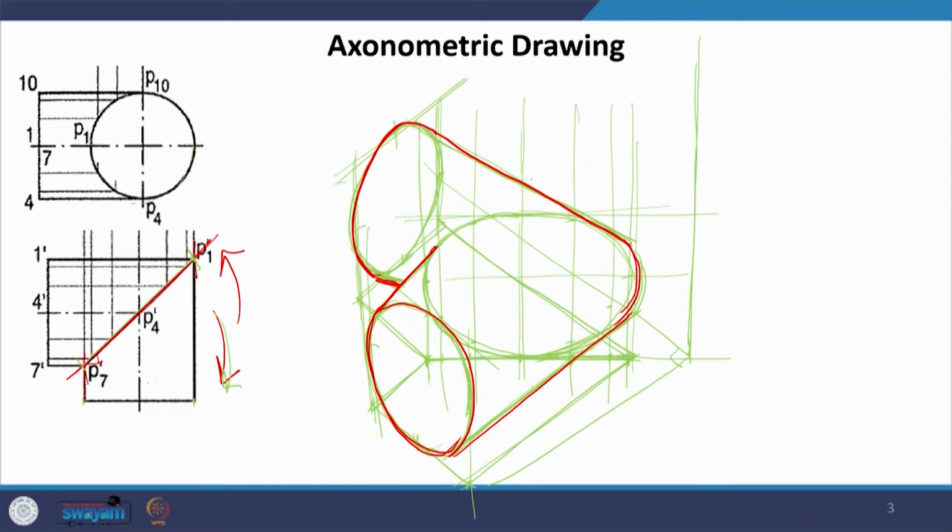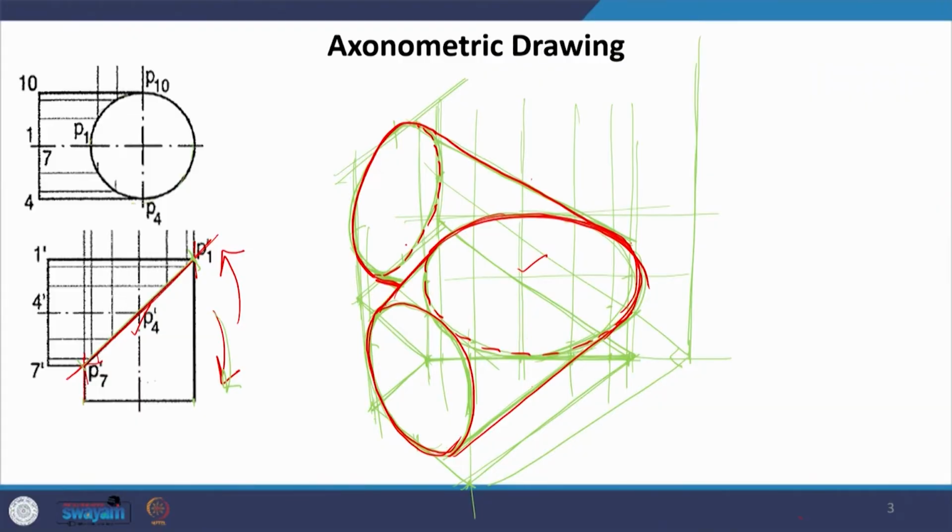And here at this level, we will be actually seeing this curve coming. That is how you will be seeing this combination of two cylinders which are welded, joined at this level, and this is the dotted, the hidden line which is going to go behind. Now, if you can see very clearly, this ellipse is actually the true shape of this intersection, where these two solids are coming and intersecting each other. So, this ellipse is going to be the true shape.